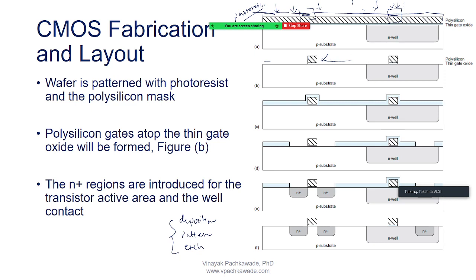So what I see is that the polysilicon gate is standing on top of the oxide. You see here is the thin layer of oxide, here is the thin layer of oxide. So I have managed to fabricate the gates of the transistors, because here I will have N plus, here I will have P plus. Did you follow my step? Yes, sir. Yeah, simple, huh?